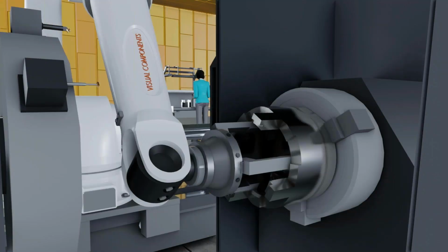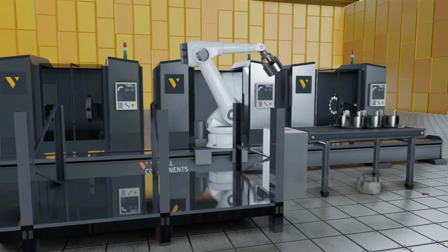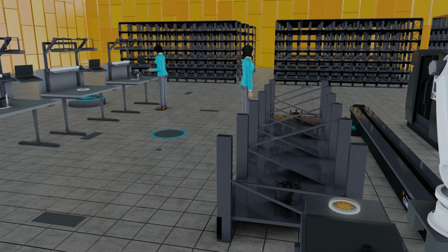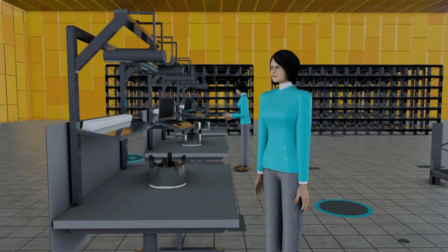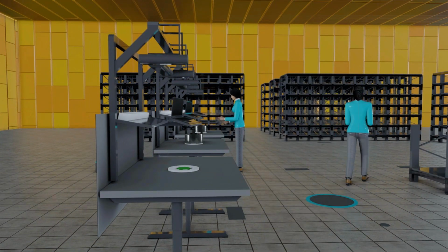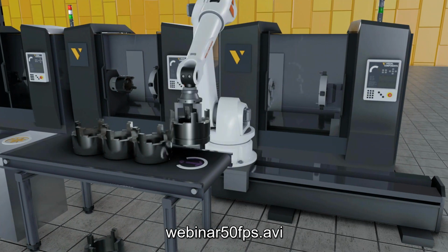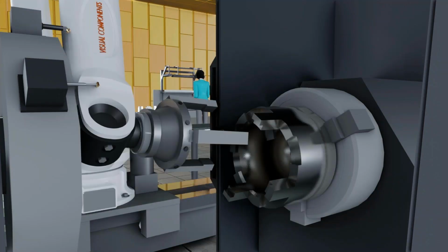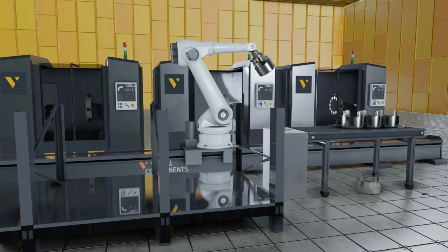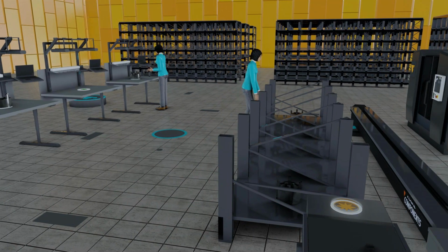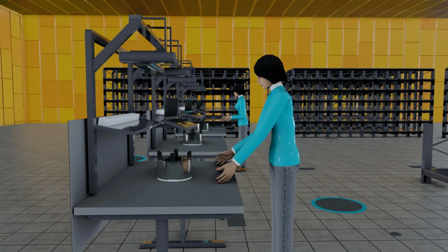Then what version do you need to have from Visual Components to be able to program the robot offline and then download to the real robot? Basically, you can do the simple robot teaching in every version of the software, as well as have these sample post processors. So that is available already from Essentials. There is nothing added in the professional version related to robotics. It's only the component modeling, but on premium, you get the advanced robotics package with path planning, curve teaching, and virtual topology, as well as paint visualization. And this would be the offline programming version with more content and features.